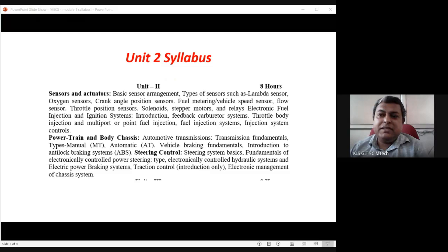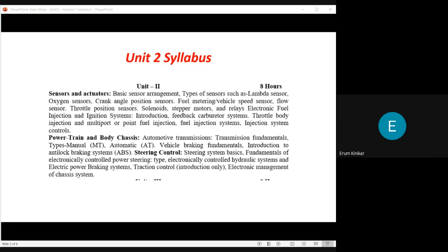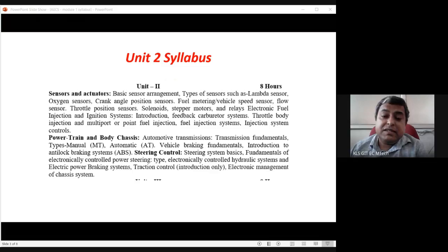Understandable. So what does a sensor do? A sensor takes any physical parameter and converts it into an electrical signal. Here it converts light into a change of resistance, and resistance is an electrical quantity. If you connect the LDR with a Wheatstone bridge or to a supply, the voltage across the LDR is the indicator of light or dark. As soon as it is dark, the resistance of the LDR increases and the voltage across it increases. In a lit scenario, the voltage across the LDR becomes very less. That is the indication of a light situation.